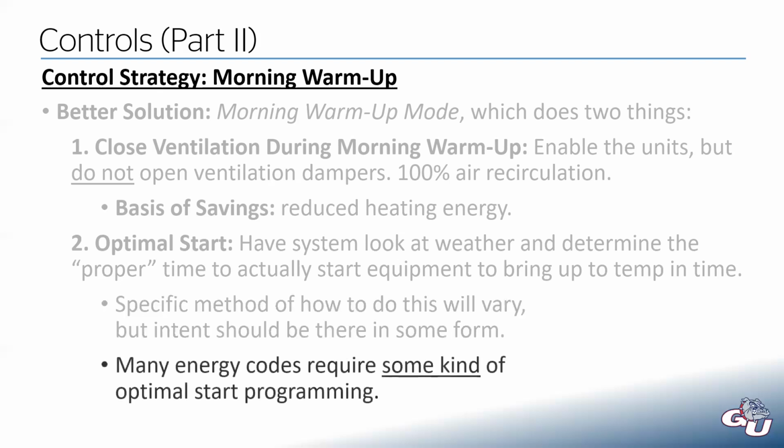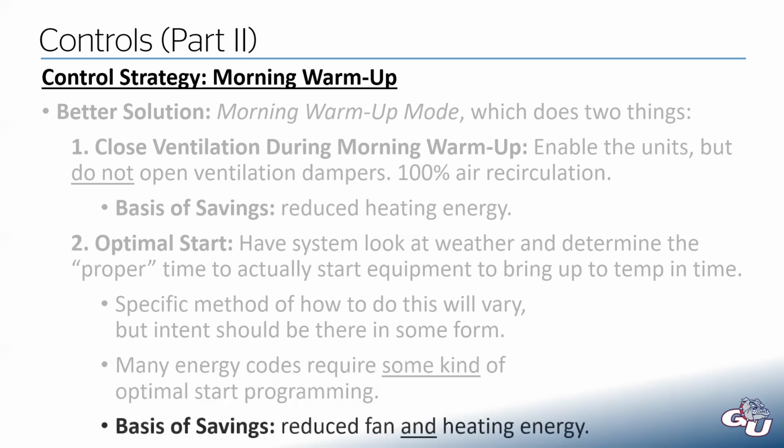And most energy codes nowadays require some kind of optimal start programming, in addition to closing the ventilation dampers during morning warm-up, because that morning warm-up period is still unoccupied, so we shouldn't be bringing in ventilation. So the basis of savings with the optimal start is we can reduce our fan energy and our heating energy by optimizing when we actually turn on that equipment.